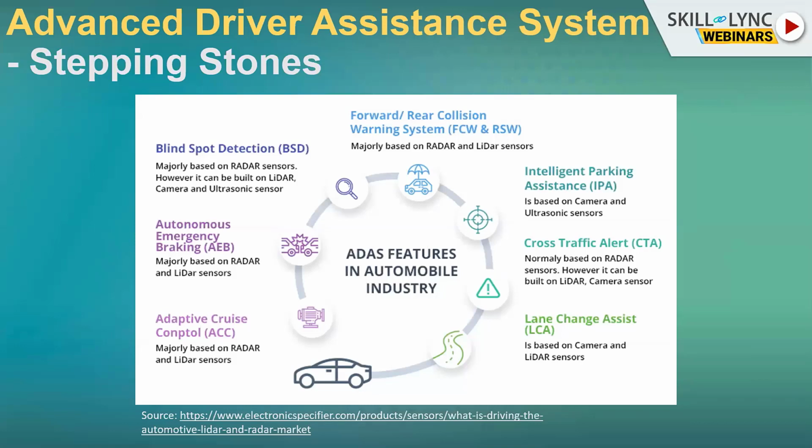So let's assume we are driving in the middle lane. This feature continuously monitors whether we have crossed over the lane lines or not, and in case we are crossing, it tries to bring us back into the center of the lane. So we can combine all these features. Or let's say the car in front of us is suddenly driving at 40 and then suddenly slows down. We can use the emergency braking feature as well to slow us down. So it's actually a combination of these small independent features that can be fused together to build up more complicated systems, bridging towards level 3 and level 4.